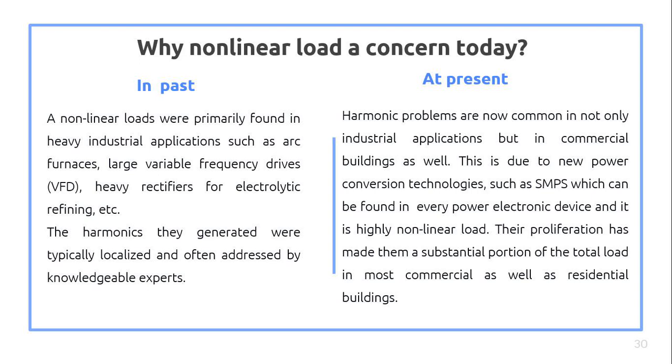Why is nonlinear load a concern today? In the past, nonlinear loads were primarily found only in heavy industry applications such as arc furnaces, large variable frequency drives, heavy rectifiers for electrolytic refining, etc. The harmonics they generated were typically localized and often addressed by knowledgeable experts and mitigated by only passive filters because they were concentrated at one point. But in today's scenario,